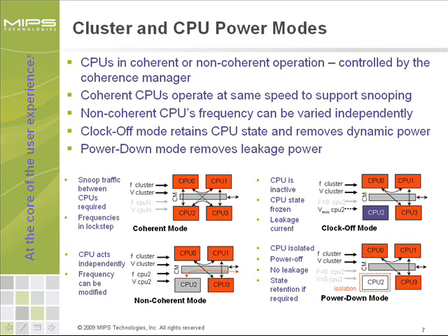The right bottom picture finally shows CPU 2 in power-off mode. Local supply rails for this CPU are gated off, and special isolation values are driven towards surrounding logic. This is a requirement since CMOS logic inputs cannot be left undriven. Specialized standard cells provide a switchable isolation behavior.